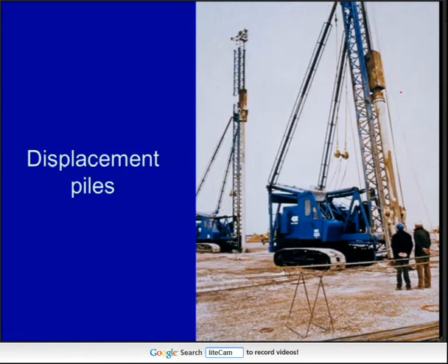Well, we said soils, when they mobilise their strength, may have a peak strength before softening to critical state. We said the difference between the constant volume strength, and I said critical state there. I apologise. If I use the words critical state, just hear the words constant volume. You'll see why I use that phrase occasionally, because in the last part of the course, it's a model called critical state soil mechanics, which explains the behaviour we see.